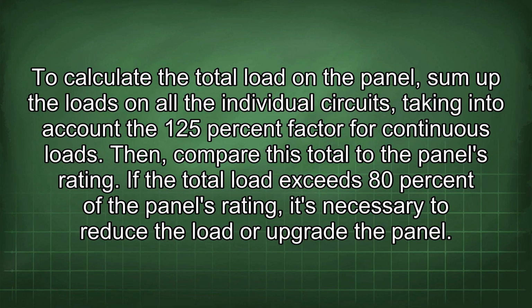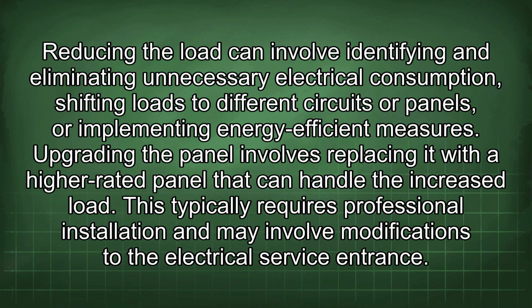If the total load exceeds 80% of the panel's rating, it's necessary to reduce the load or upgrade the panel. Reducing the load can involve identifying and eliminating unnecessary electrical consumption, shifting loads to different circuits or panels, or implementing energy-efficient measures. Upgrading the panel involves replacing it with a higher rated panel that can handle the increased load. This typically requires professional installation and may involve modifications to the electrical service entrance.